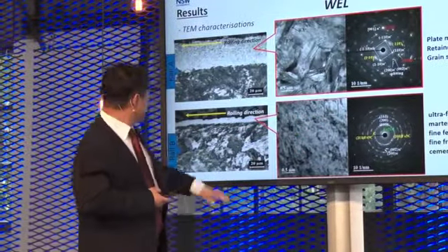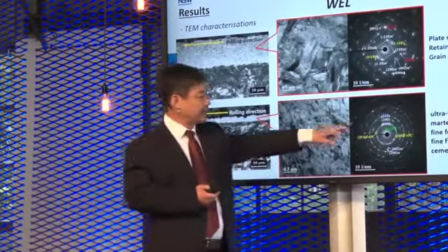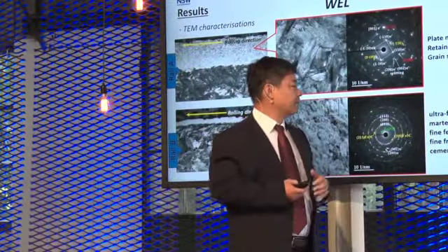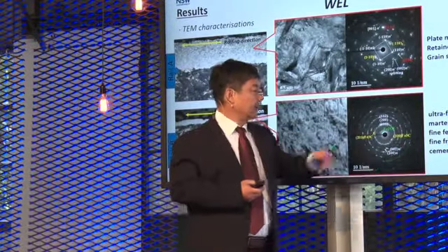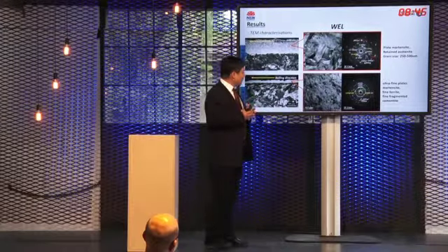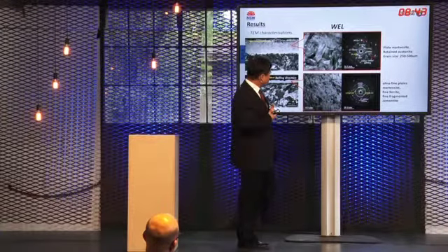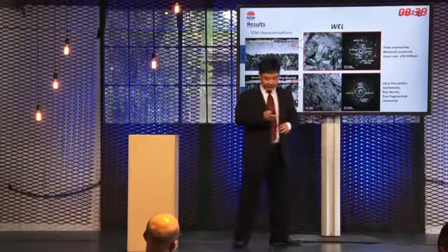For rail B in the steady traffic region, it consists of ultrafine plate martensite. Actually, we also find some fine ferrite and fragmented cementite. To gain a more fundamental understanding, we analyze a smaller region.